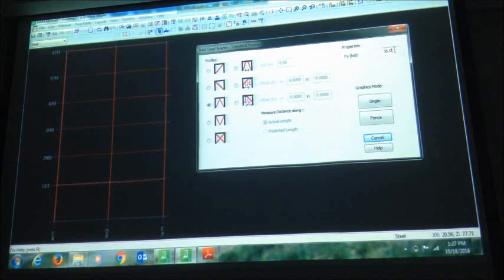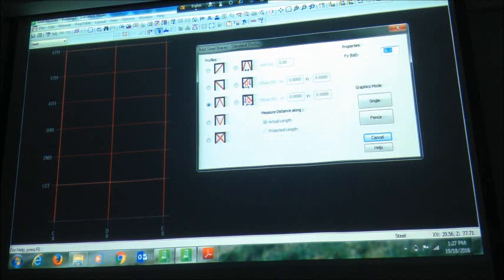I think so. And your KSI, usually for braces we use HSS rectangle sections, commonly. Sometimes we use wide flange sections, but it's kind of difficult, because your braces are all in compression or tension. Tension doesn't have a problem, but when it is compression, you want it to buckle or bend in a way that you can define. Now, if you place a wide flange section, just like your column designs, it will buckle about the weak axis, right?